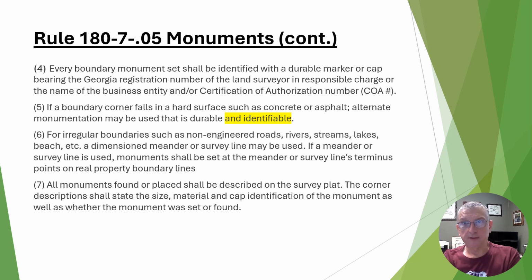I personally use a good 1.5 or 2.5 inch magnetic nail, and we have washers that are stamped on them with the company name and phone number, just like our plastic rebar caps are. They must be durable and identifiable. The little plastic washer things that you put on some of them are flagging. That's not identifiable, it's not durable.